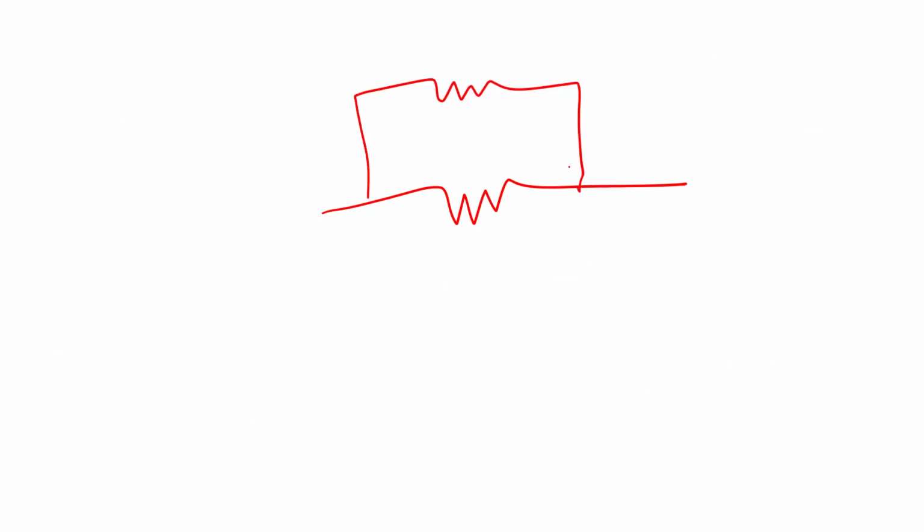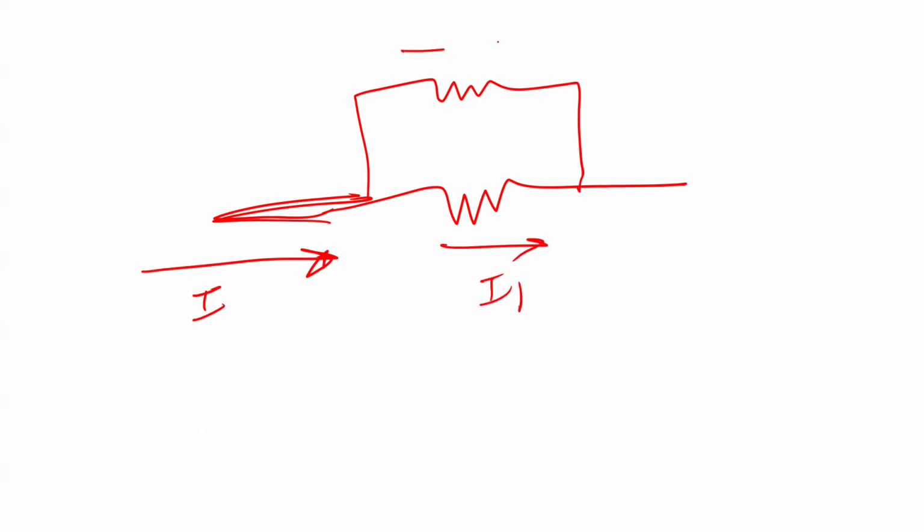And you can learn something related to this, related to circuits, very important. Listen to me. If you have a resistance this way and a resistance this way, and a current I here, this current should split into, for example, I1 and I2. Keep in mind, current means charges, and these charges are not going to go anywhere. So the certain amount of charges here should equal the summation of the charges in these two branches, because the current is not going to fly away. You understand what I'm saying? The same charges here are going to split this way. Yes, that's true.